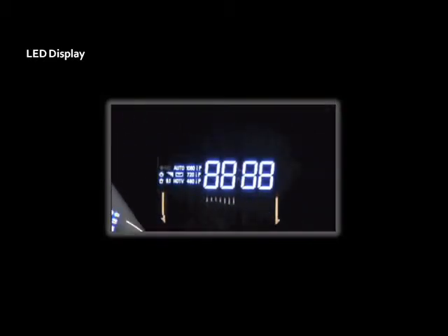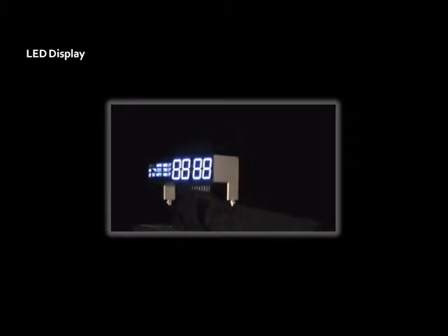LED displays are used in many different applications, including automotive, industrial, audio-video, and consumer products. Each segment in an LED display can be custom shape and size and is driven independently from the other segments. The segments can be driven with static voltage or multiplexed using PWM to control the brightness.